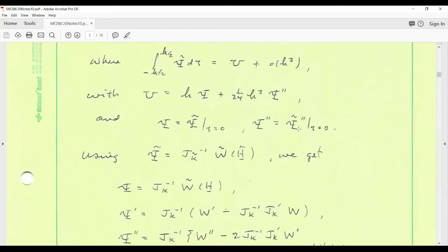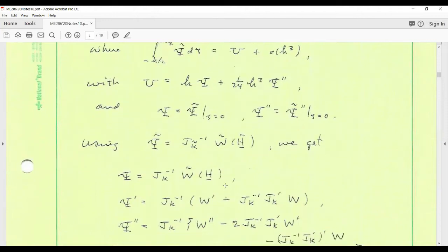Okay, so now the issue is to write this, say, in terms of our strain energy function that we're using in this theory. Psi is 1 over the determinant of k evaluated at the midplane times the three-dimensional w evaluated for when h is on the midplane. So h tilde on the midplane, I'll just call it h without the tilde.